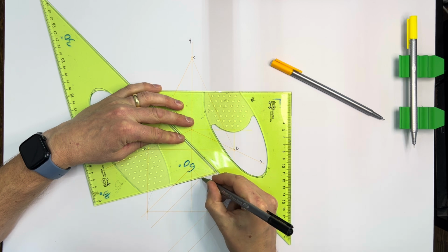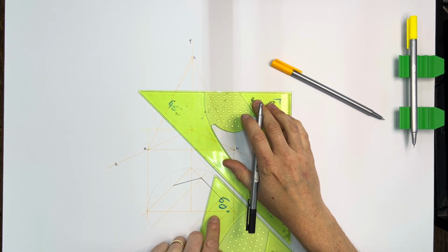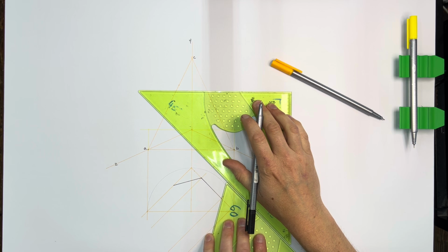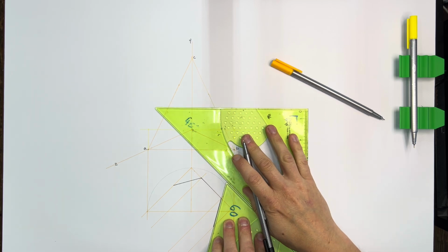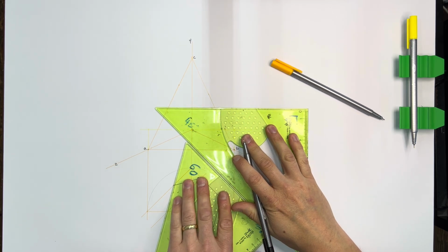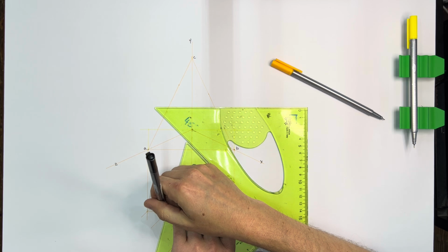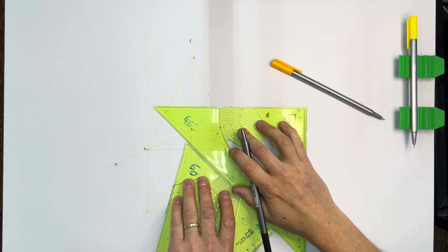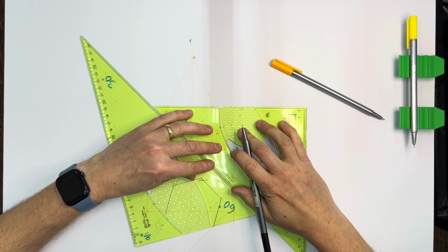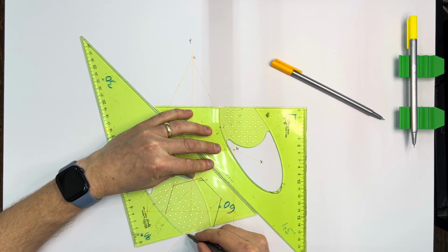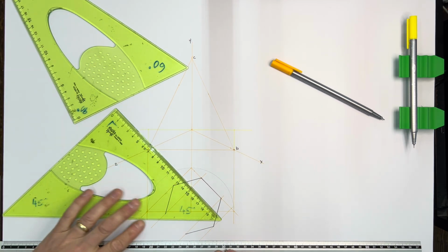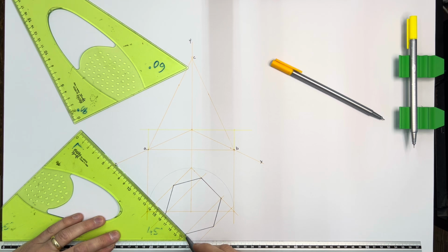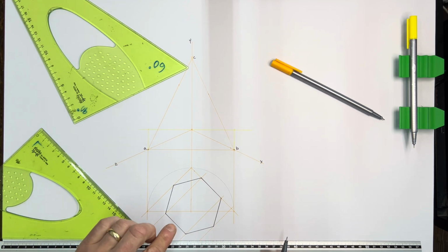So I harden in that line, and turn it around in this direction to get 60 degrees in the other direction. Of course, you can use your protractor for this as well. And there's 60 degrees there. Now, keeping the set square at the same angle, so 60 degrees here, that gives me that length of side. Flip it back in this direction. So this is why the set square method would be more efficient than using a protractor. And then these lines should line up perfectly at 45 degrees. That would be down to having sharp pencils and using your equipment accurately.